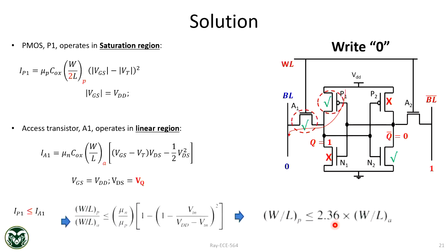When this voltage starts increasing, we're increasing our overdrive, so we still hit equilibrium, even though this has a bigger W/L.